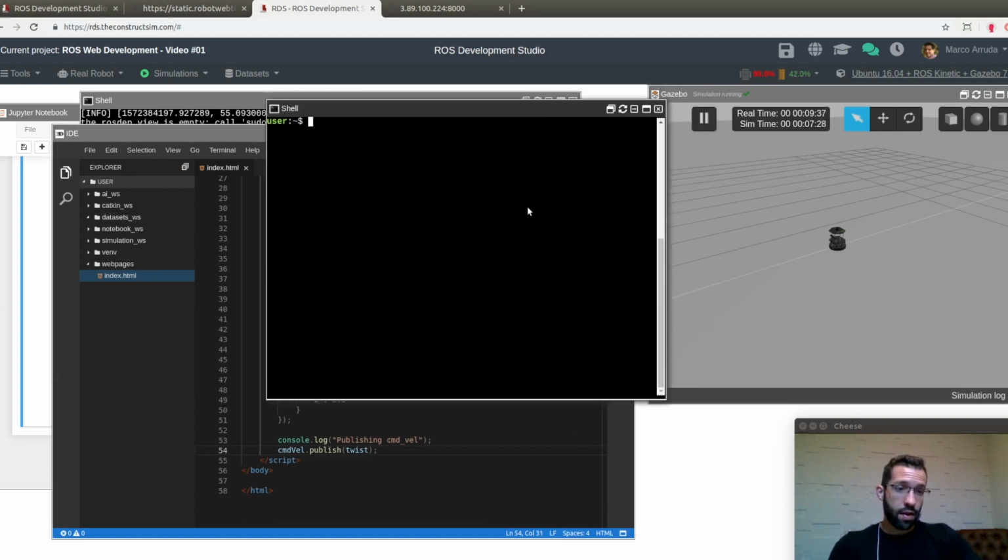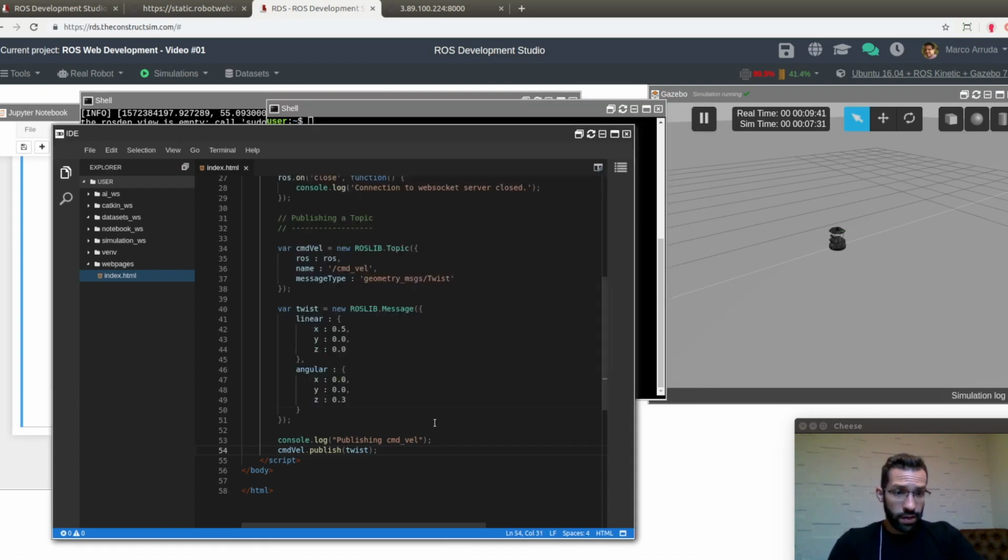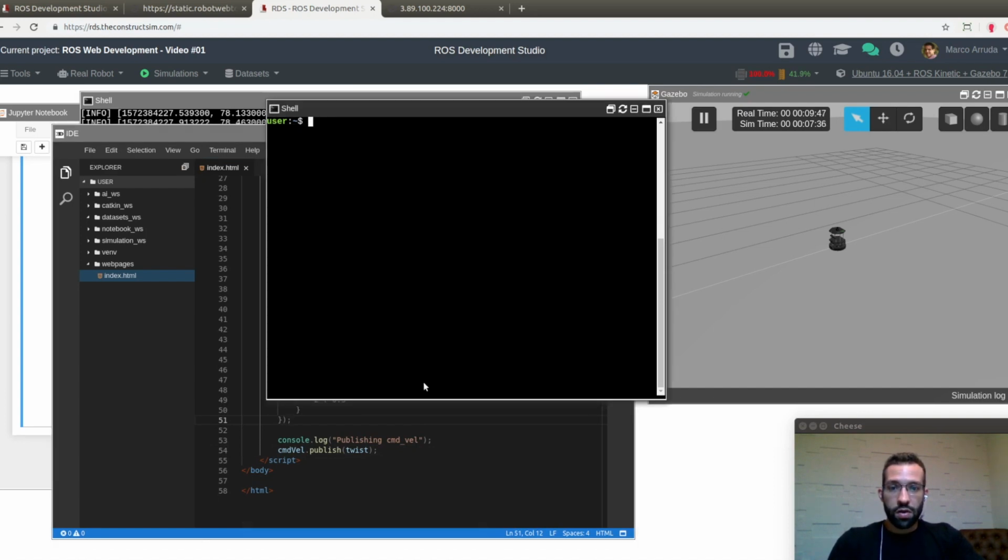So how many messages are coming? Is it happening just once, or are we defining a publisher with a specified rate? Actually, we are not, but let's make sure, okay? So let's do a rostopic echo cmd_vel, and we are going to receive any message that comes to this topic.